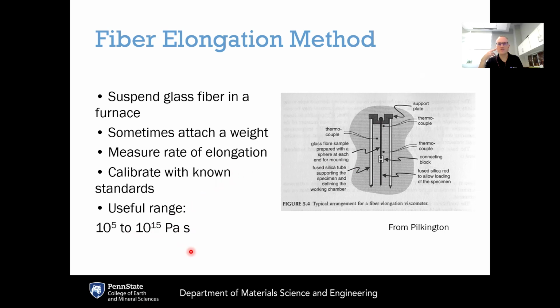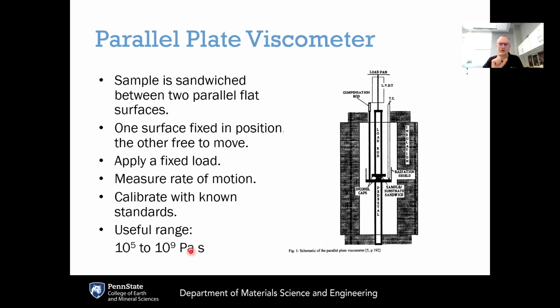So I personally consider fiber elongation to be kind of a quick and dirty method to give you an estimate of viscosity, but I wouldn't recommend using this to give you very precise values. A better approach in this intermediate range of viscosities is the parallel plate approach.